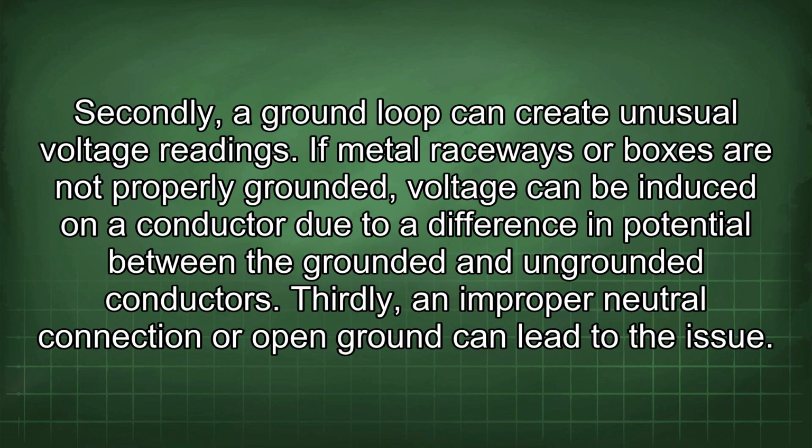Secondly, a ground loop can create unusual voltage readings. If metal raceways or boxes are not properly grounded, voltage can be induced on a conductor due to a difference in potential between the grounded and ungrounded conductors.